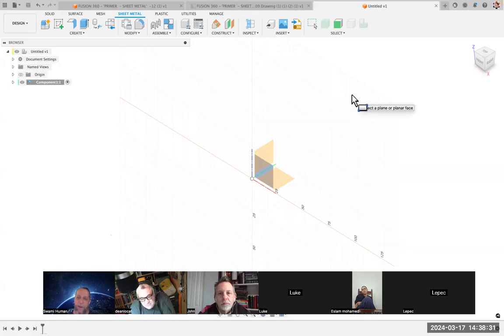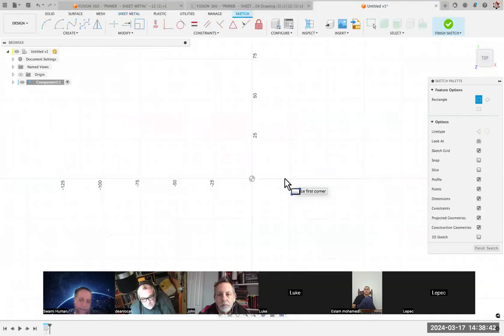All right, so everybody is in Z up, and the tool is waiting to make our rectangle, saying where do you want to put it? Let's go to the ground plane. That's our XY, our red-green axes right there. Click that. It automatically takes us into the sketch mode. Over here are the types of rectangles in our sketch palette on the right. I'm going to choose the center rectangle. Let's hover over the center point. It'll lock into there. So click on it, let go, drag, glide out.